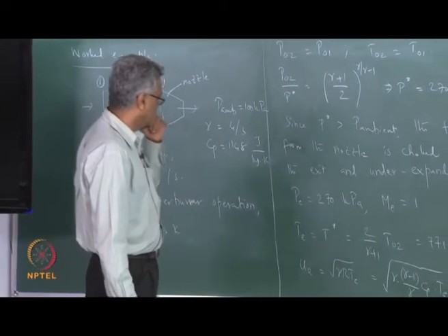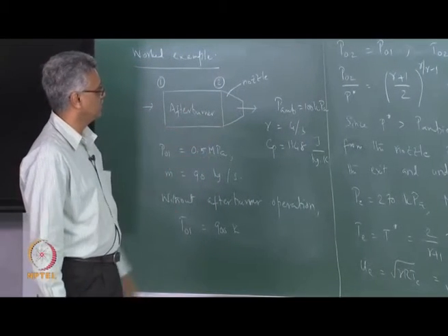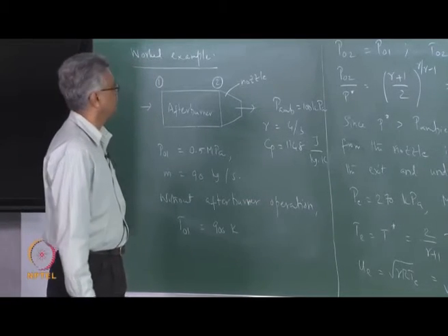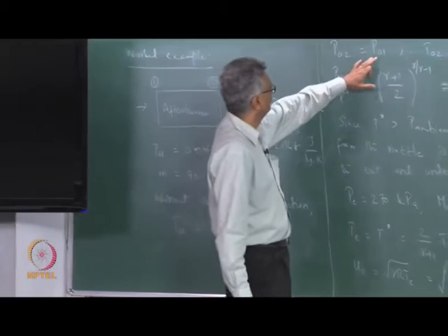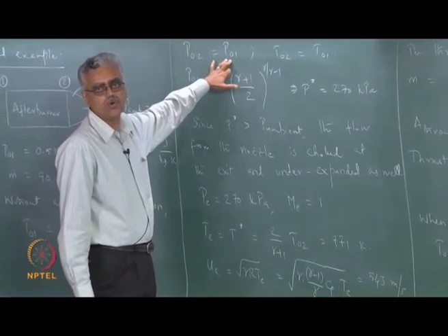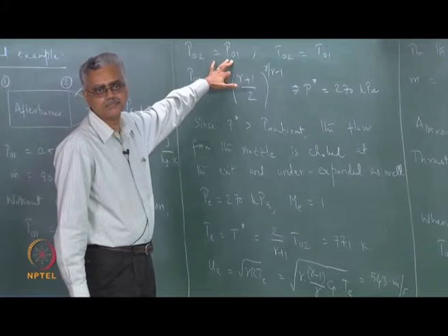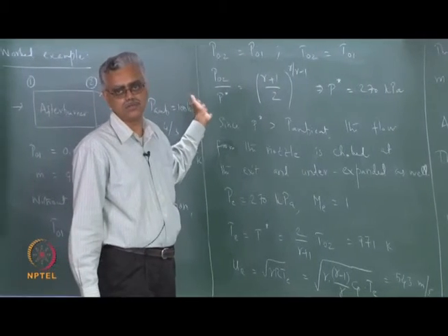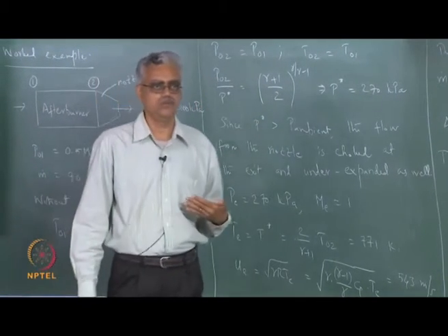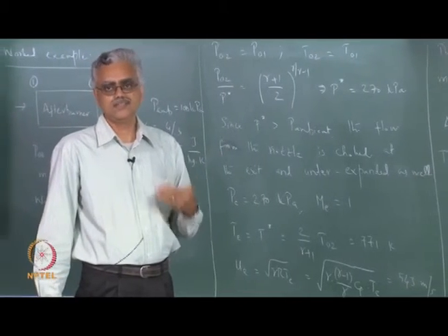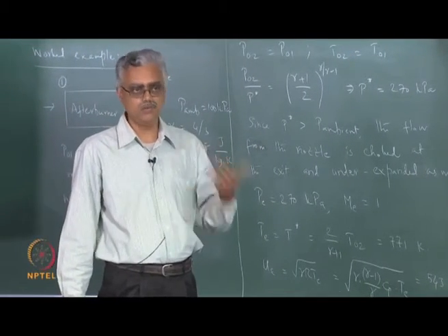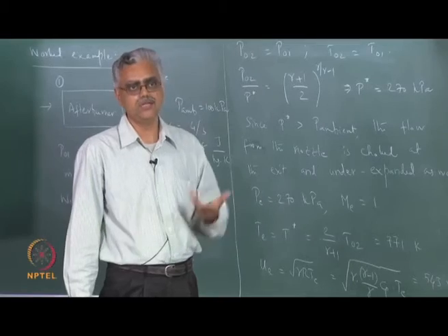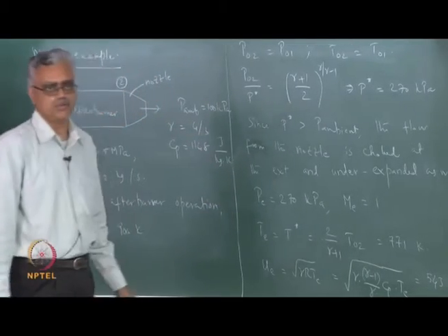Okay. Now, one point that we discussed earlier has to do with P0 over P ambient. Now, if you take the case without afterburner operation, you can see that P0 is 500 kilopascal. So, P0 over P ambient is 5, correct. The question is, since P0 over P ambient is 5 and I am using only a convergent nozzle, if I had used a convergent divergent nozzle, how much would the thrust have increased? Would I have gotten a lot more extra thrust, or is it about the same, not worth doing a convergent divergent nozzle? We will examine that next just to complete the problem. Okay.